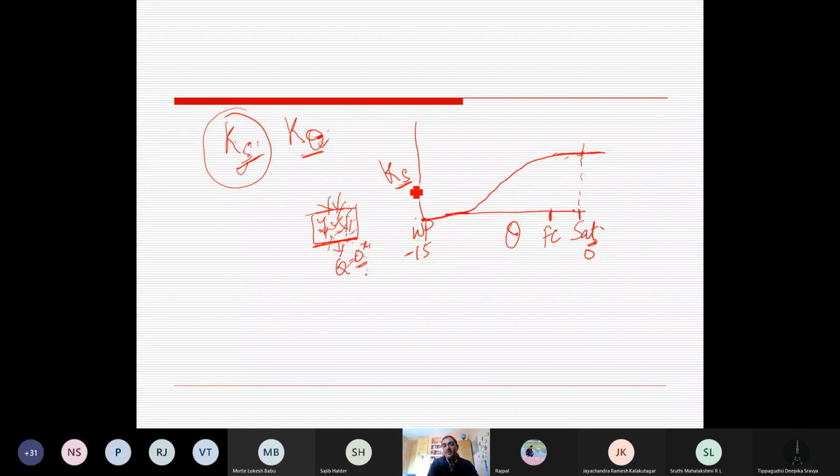So in the hydraulic conductivity versus soil moisture content relationship, once it is saturated, that's why it is called saturated hydraulic conductivity, it is constant. No matter what the level of water is, it is constant. The reason is you cannot increase water content inside the soil after saturation. So hydraulic conductivity is maximum and constant here. But before that, it is less than this constant condition at saturation, and if moisture reduces, the conductivity of water from this soil is reduced.